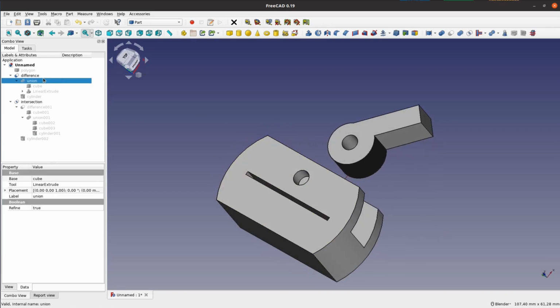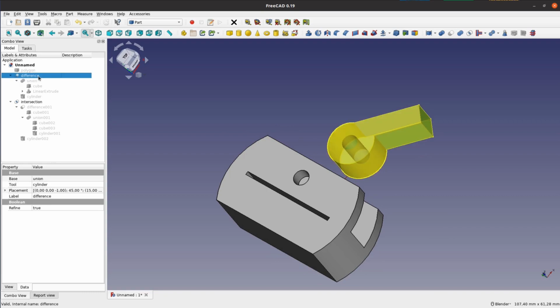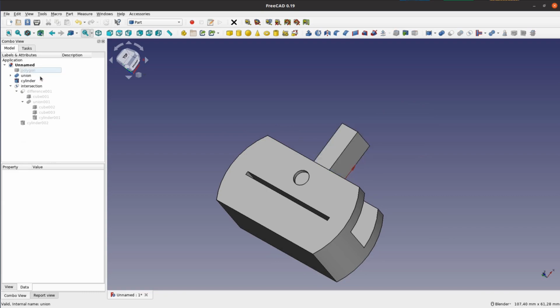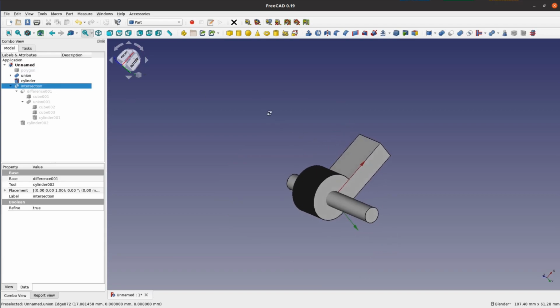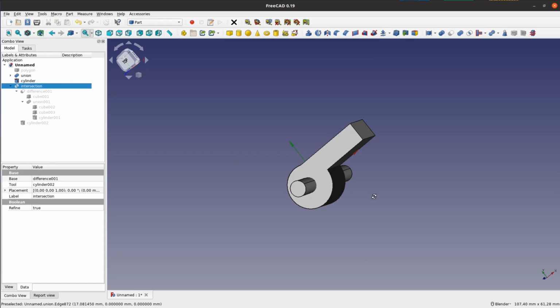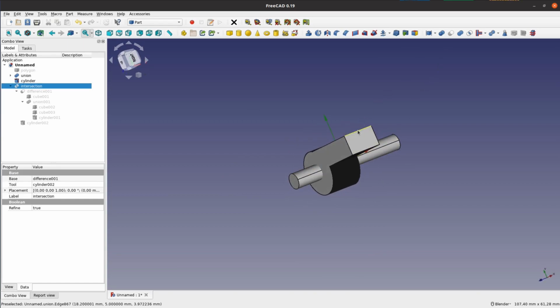If we delete a Boolean operation, we can change the individual parts of the assembly. One thing that I use FreeCAD frequently for is to add a fillet to my OpenSCAD models, as this is quite a pain in OpenSCAD itself.